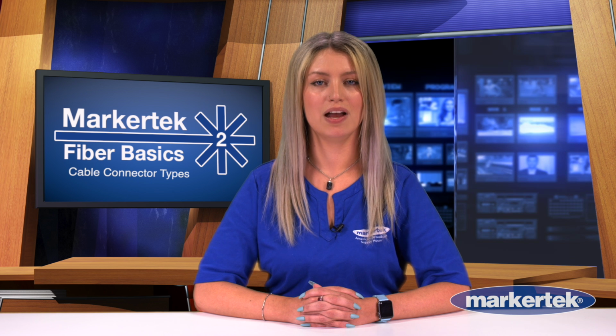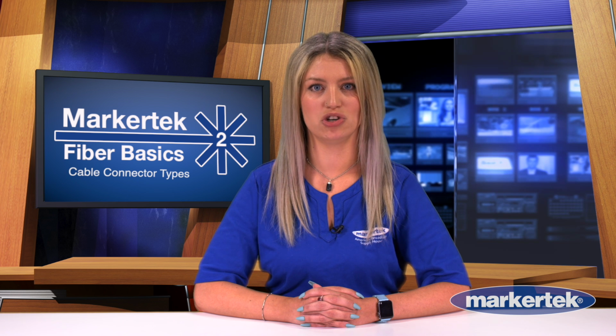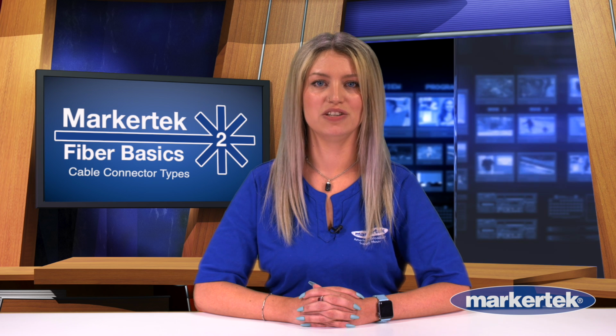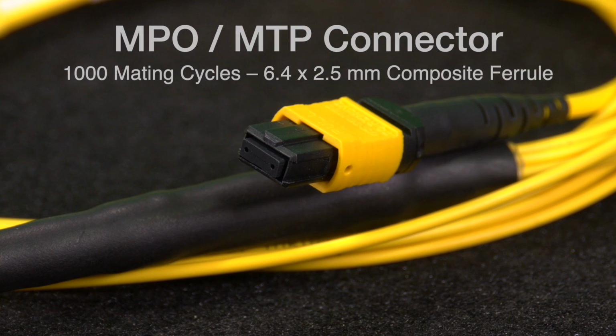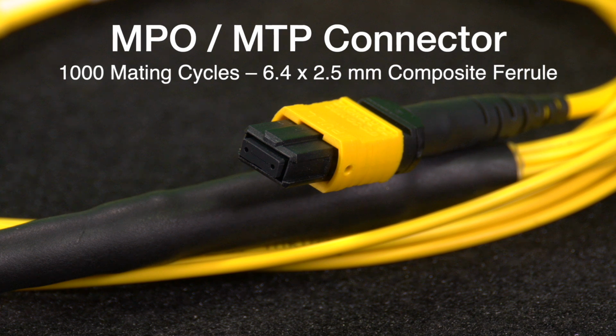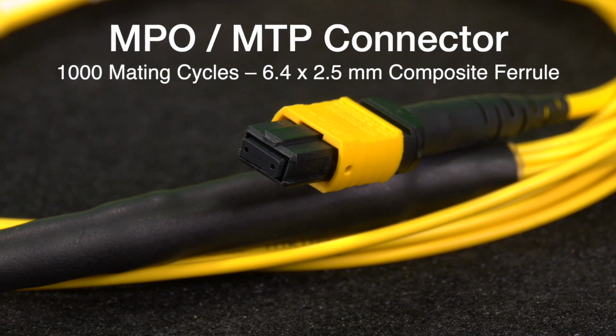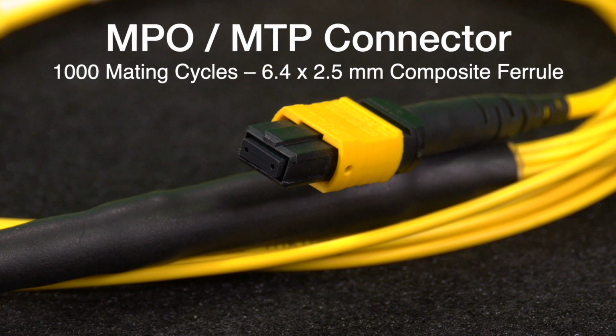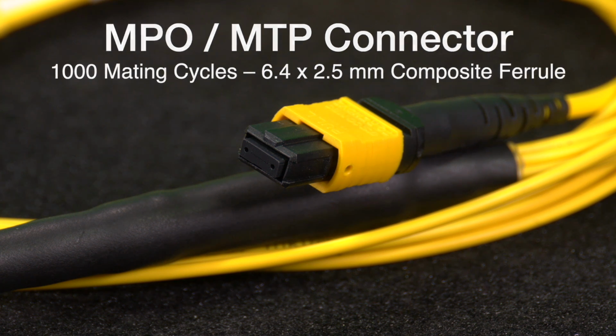Finally, there's MPO, which is short for multiple push-on, and these are typically available with 8, 12, or 24 fibers. There is also the MTP connector, a registered trademark of US Conec, which is essentially the same connector type. MPO and MTP connectors are 100% compatible and interchangeable.